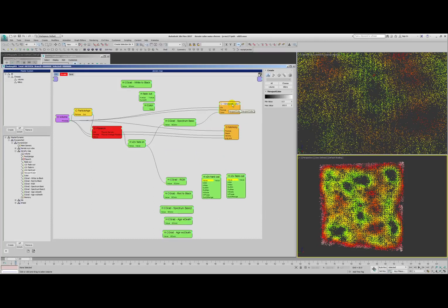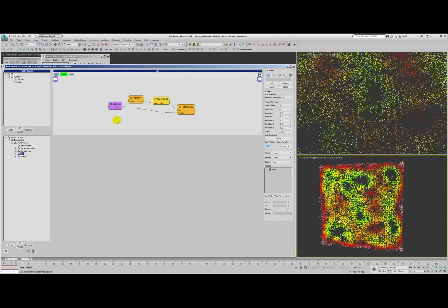Viewport color in order to visualize the particles at birth, do a p-search, figure out what's my density of the surrounding particles, and based on that density value we color them. But we use that density in order to punch out certain holes in this next rule where they look at their density, and if it's within a certain range, in this case if it's over 120, then they are going to die to create those nice big gaps.